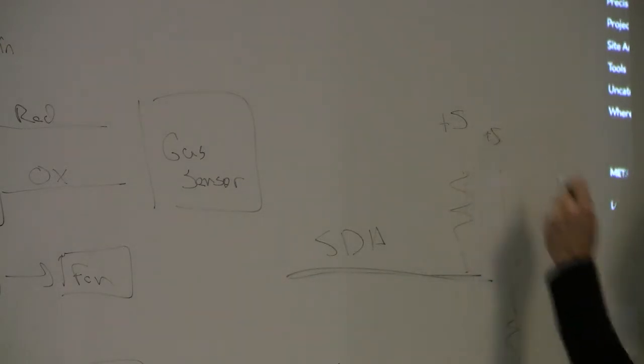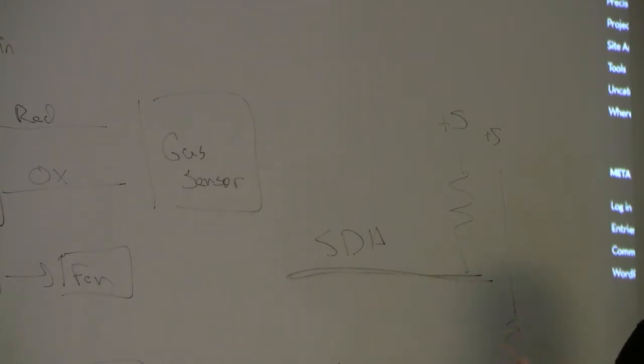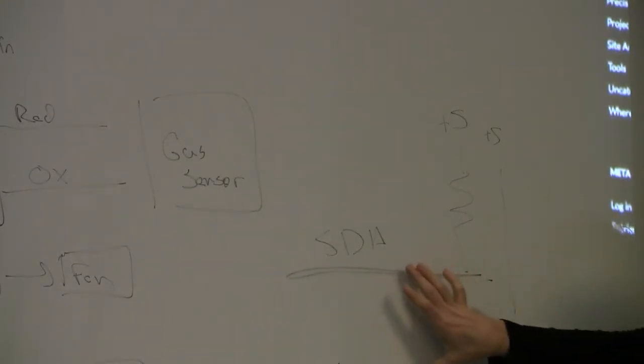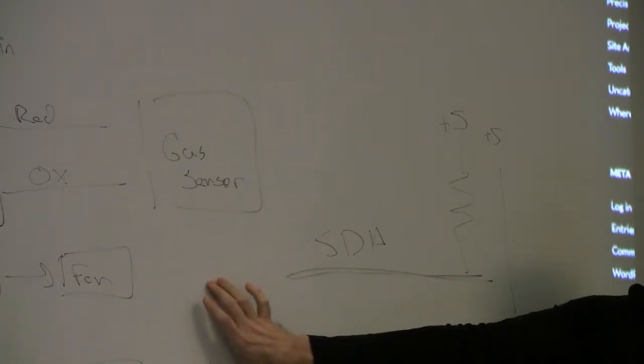Same thing here. And then the way the signals are sent on an I2C bus is the device pulls that low and then lets it go back up to send the signal. So the issue might be that you have a 5 volt signal coming on SDA and SCL, and if your Pi is sensitive to that, which it is, then that could be an issue.